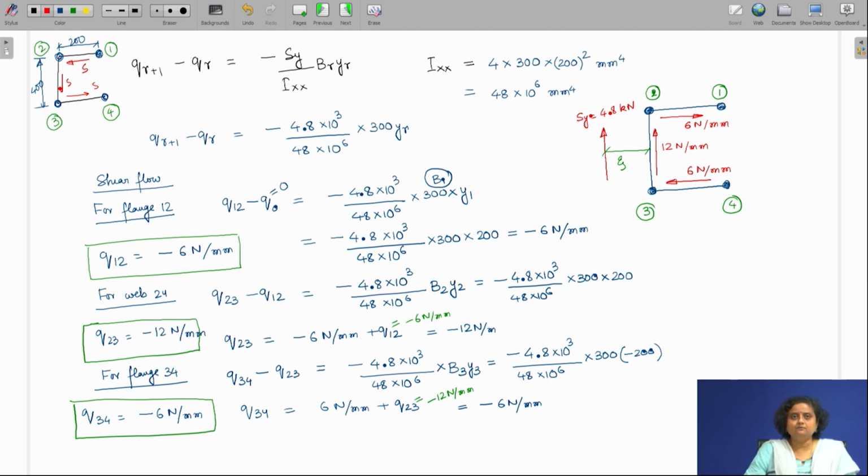Evaluating those integrals was a tedious task, making the solution of shear force problems cumbersome. In a skin stringer idealized cross section, finding the shear flow is much easier as compared to a normal thin wall beam, and therefore can give us a very quick solution or estimate of the shear flow in a cross section.